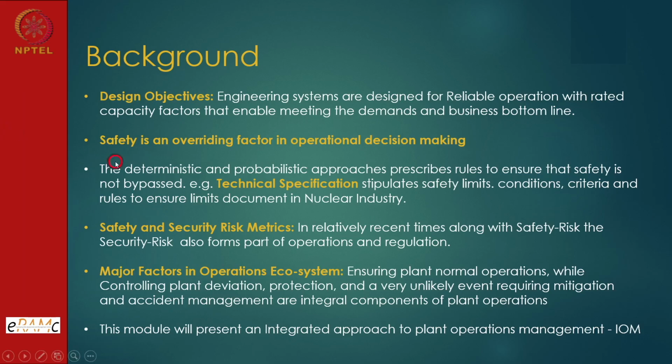And then the safety spirit is implemented in the plant, it's not only at the talking level. It is basically a document called technical specification, which stipulates the conditions called limiting conditions for operation. Then there are limits on parameters, and the topmost priority is safety limits, and all these should not be violated. In any case, if these things get violated, then it requires a regulatory review.